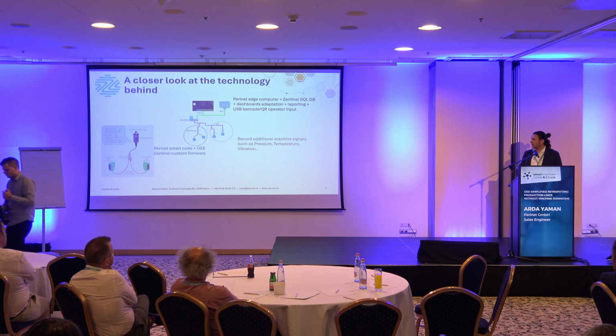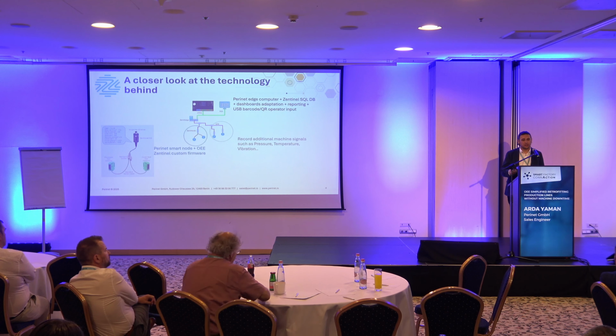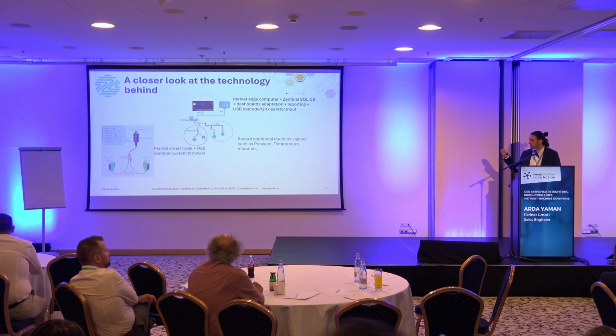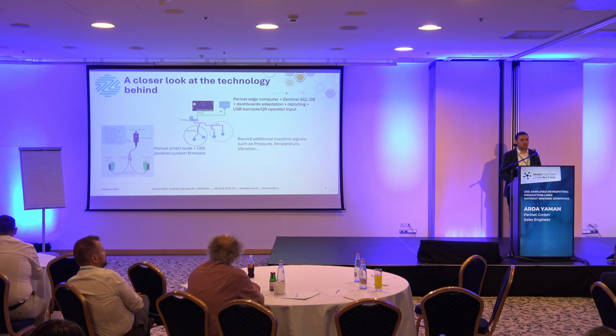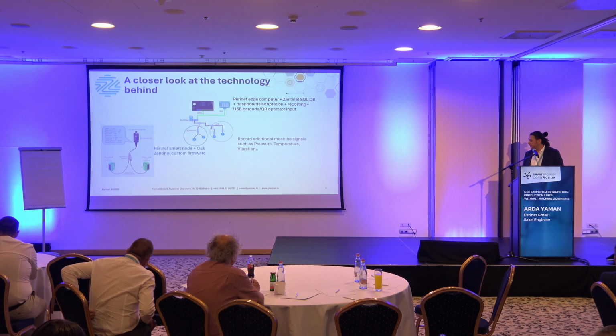First, you need to use hybrid single-pair Ethernet cables, which is really a lightweight cabling solution which carries power and data on the same cable. And these smart nodes can read from sensors, like all types of sensors. They can read 0 to 10 volts, 4 to 20 milliamps, general purpose inputs and outputs, or even we are doing some new thing which will read Modbus and directly turn it to regular Ethernet.